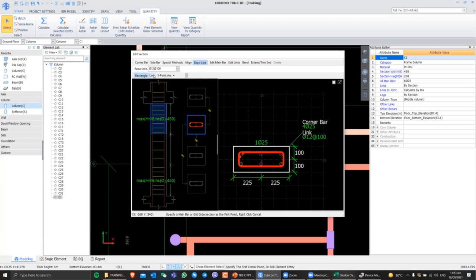And then use the command, maybe line, no? Tapos po, i-drawing nyo lang, i-connect nyo lang yung mga rebar. From here, left click, up to here, left click. If you're done, press right click to confirm. Right click is the language of the software to end a certain drawing command. Right click, meron na akong ties, no? May ties na ako sa gitna.